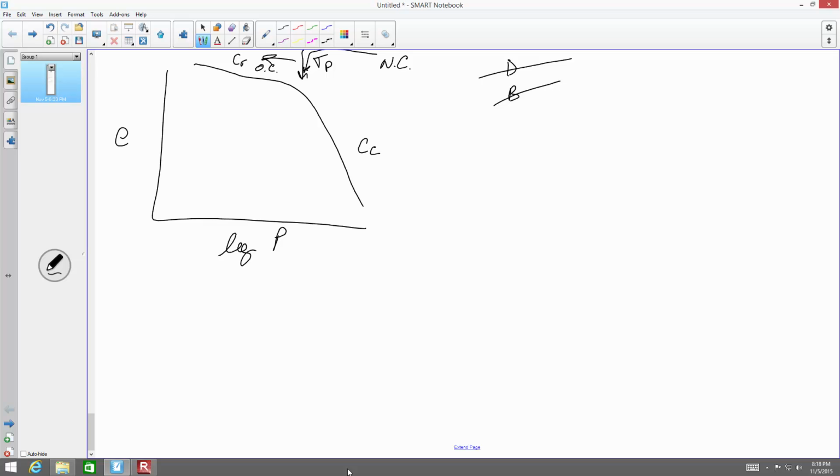If the water table rises, so if we've got a situation in the ground and the water table's right down through here, and I'm looking at the stress at that point right there, if the water table goes up, does the stress at this point increase or decrease? Decreases, because things are becoming buoyant, right? C: it will settle an additional amount if the water table rises. Is it going to settle or is it going to expand? It's going to expand. That limits it down to A.